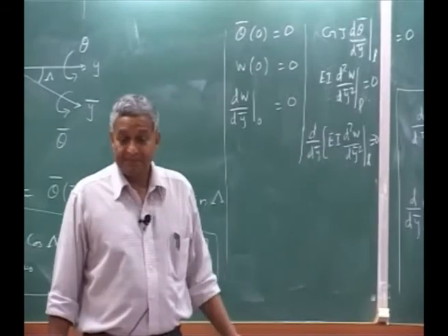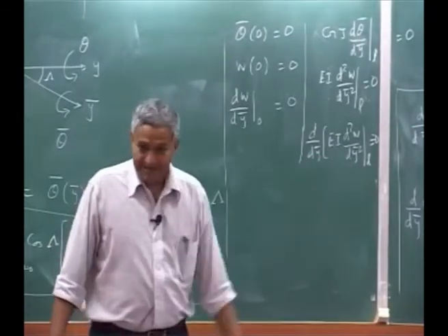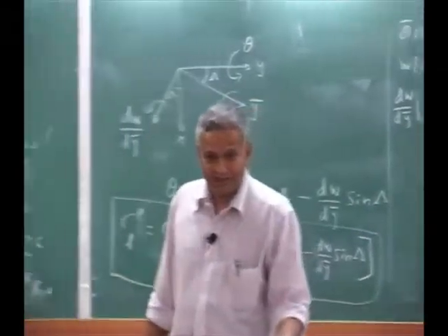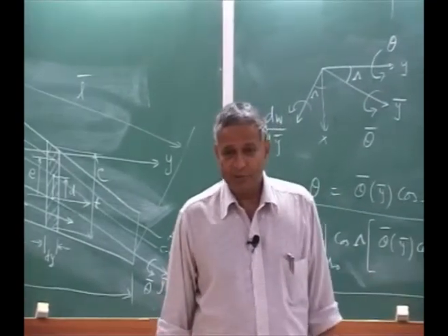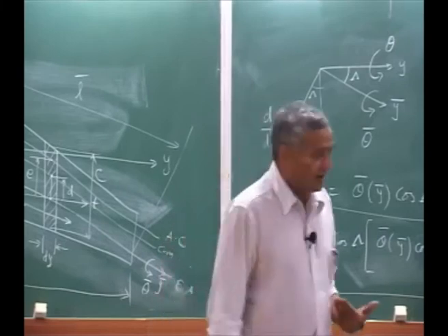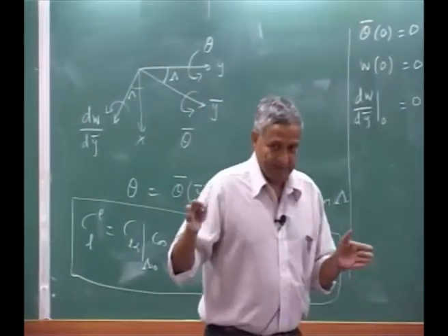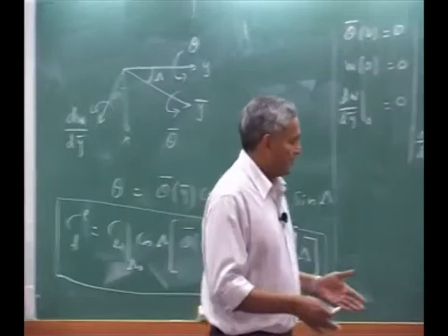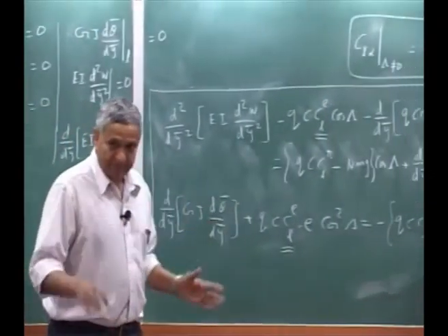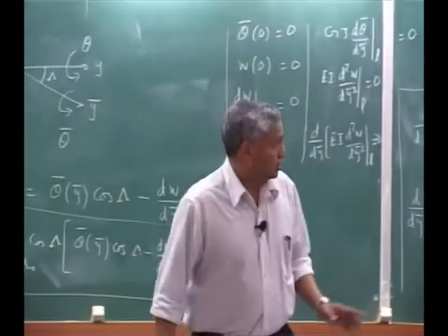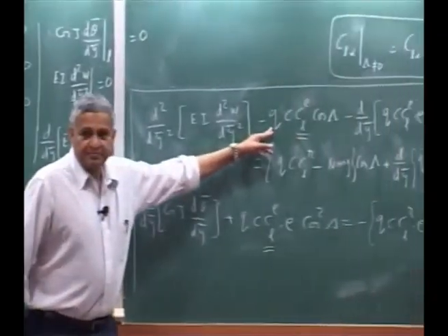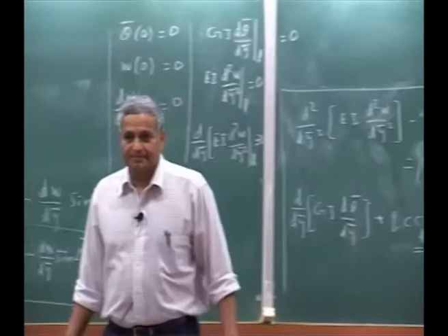Substitute them there, multiply by the assumed shape function, and then you apply the Galerkin approach. You will have a stiffness term, and another term with the Q dependent. Then solve that eigenvalue problem.